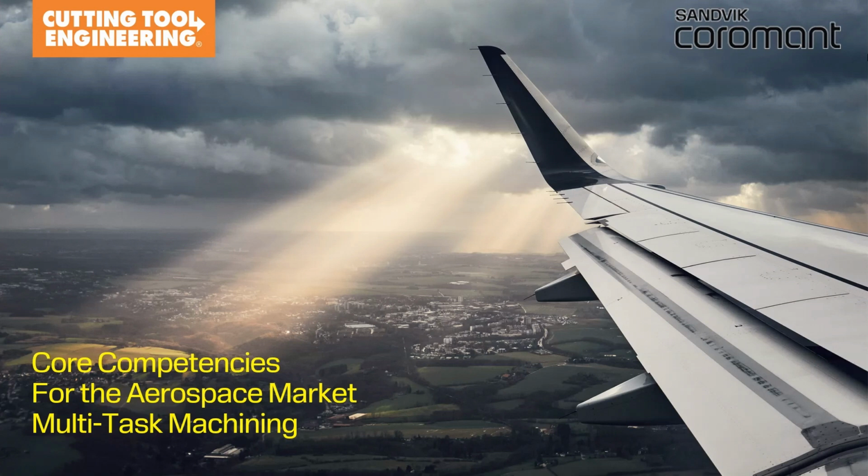So I'm going to first start off with talking about a couple of turning grades that we're going to highlight, then go into 3+2 turn machining, into full simultaneous 5-axis turn machining, and then dive into some 5-axis milling, including ceramic milling, along with turn milling and some point milling for turbo machinery, and then even discuss some really interesting solutions for skiving on multitask machines.